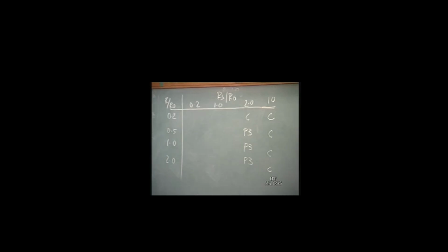When Rs and R naught become comparable, and when Rs becomes less than R naught, one has to go for transmission line analysis. So for transmission line also we have two models. One is the normal one-section transmission line, which we have already seen. But when the resistance of the line becomes comparable, that is, it is a lossy transmission line, we have to go for what is called a 4-section transmission line model.